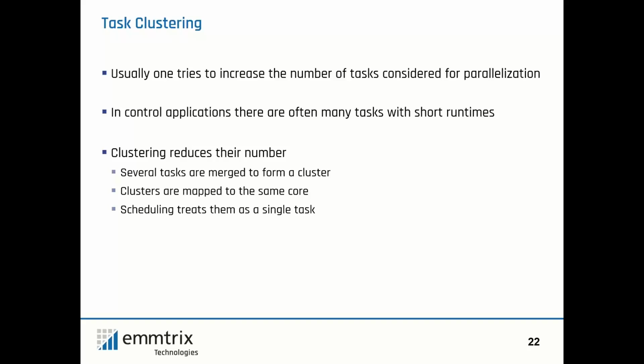So on average, 14 tasks mapped to a single task to be able to tackle the scheduling problem in that case. Okay, I was wrong there. We reduced it to 50, not 100, but this is something that is selectable in the tool. It's a trade-off you make: how much clustering you do, because clustering might reduce the quality of the parallelization in the end, but decrease the runtime. If you just want a first estimation, you do a more strict clustering, and if you want good results, you will reduce the clustering a little bit.